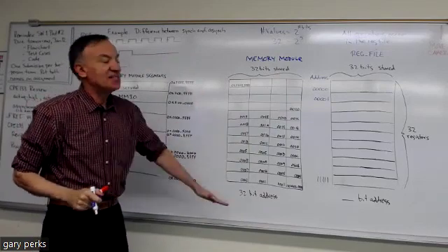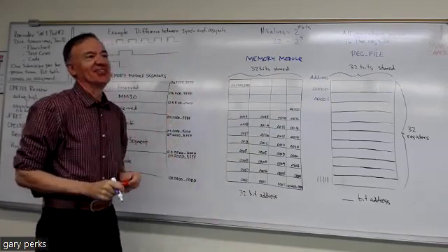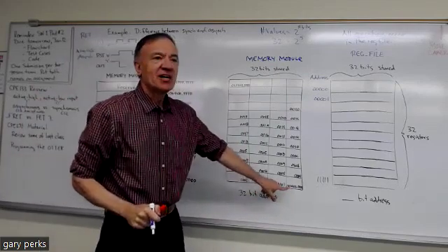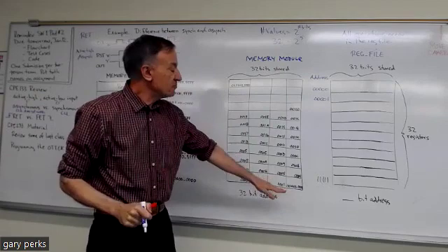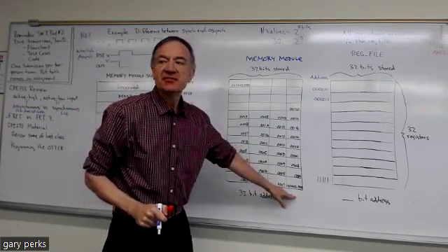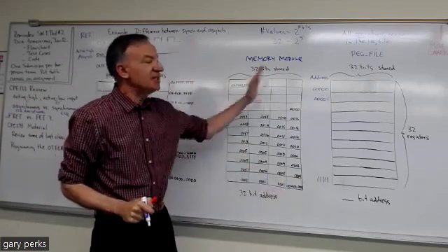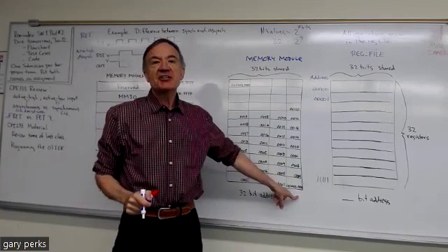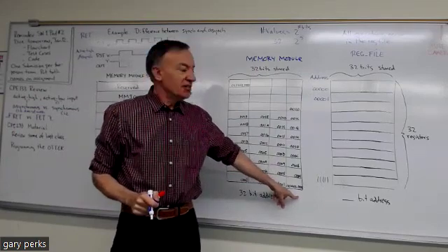But the memory module has many, many more registers, because it starts at address 0, and there's 32 address bits for the memory module. So in the memory module, each register can hold 32 bits, and each address is 32 bits.